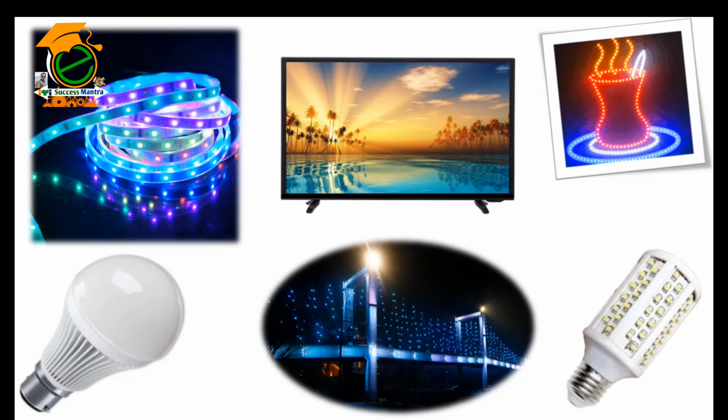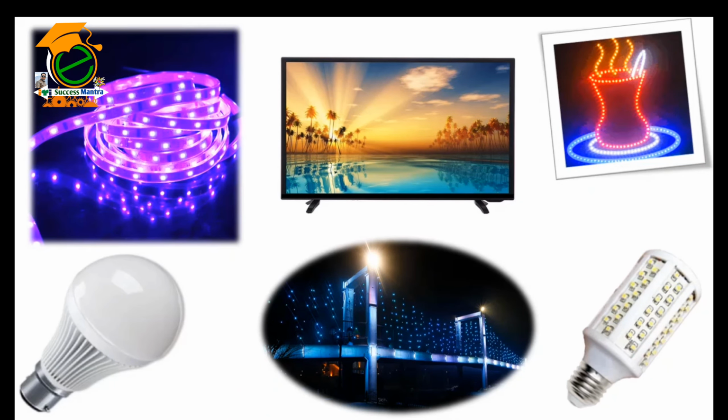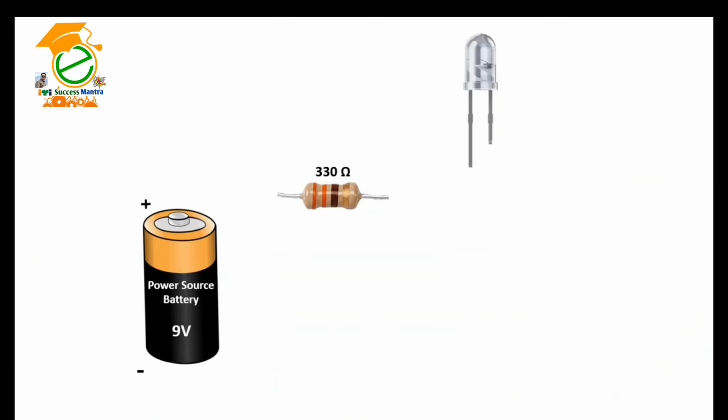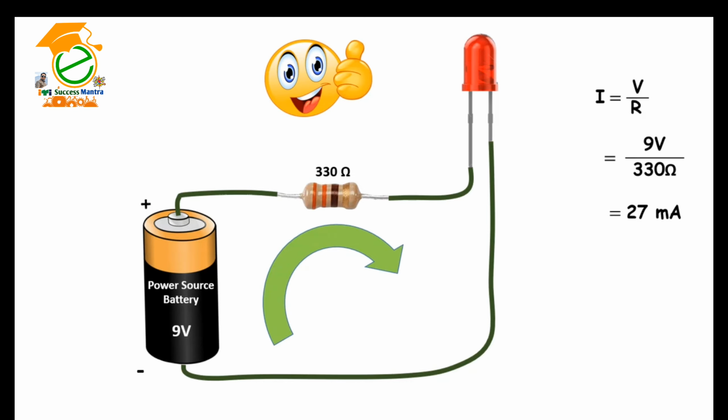There are typically 2 indicators to let you know what direction electricity will pass through an LED. The first indicator that the LED will have is a longer positive lead, the anode, and a shorter ground lead, the cathode. The other indicator is a flat notch on the side of the LED to indicate the positive anode lead. Like all diodes, LEDs create a voltage drop in the circuit, but typically do not add much resistance. In order to prevent the circuit from shorting, you need to add a resistor in series.